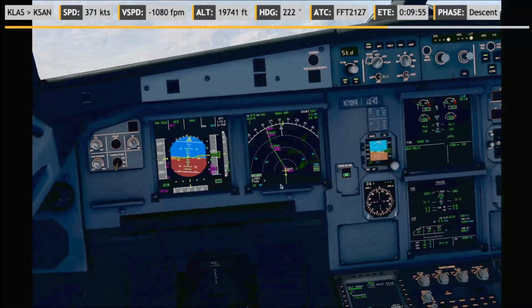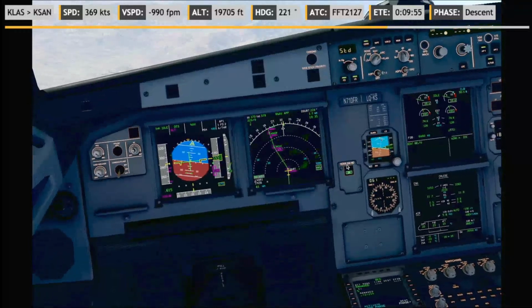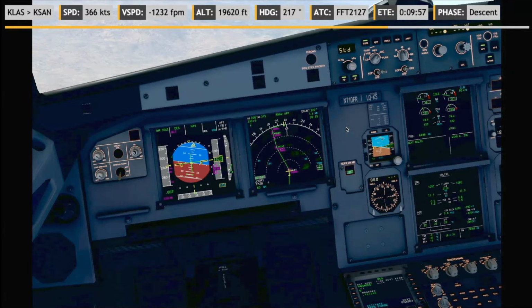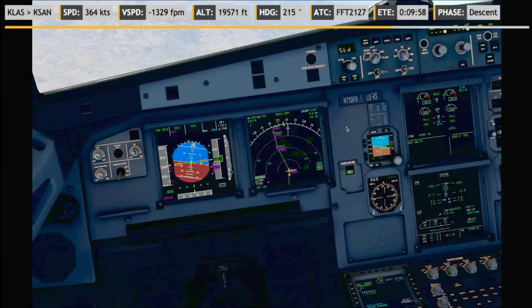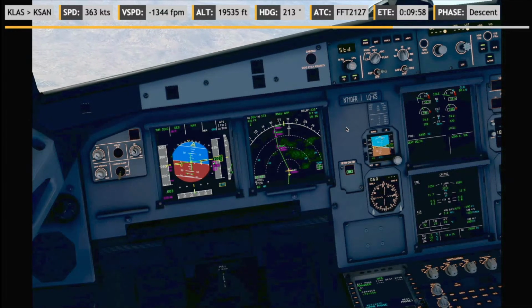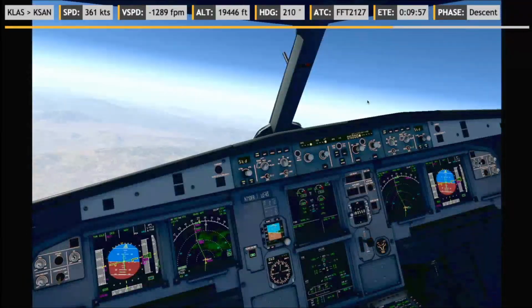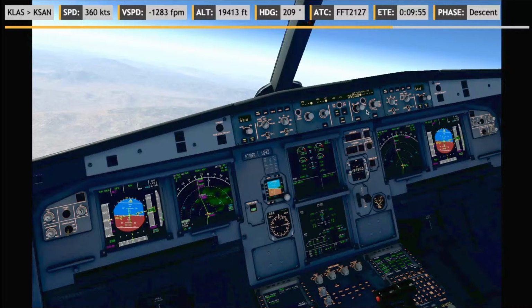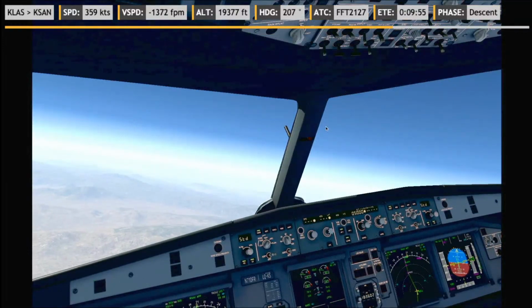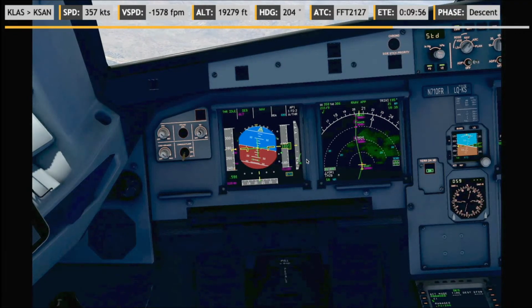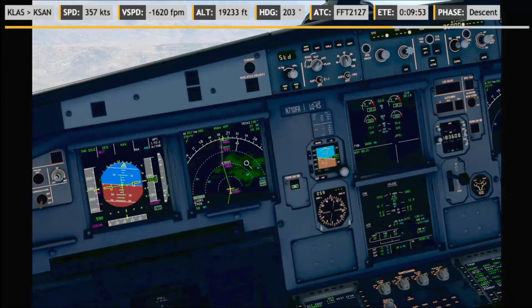190, but we're coming up on the next one. Next restriction is 12,000 feet. We're approaching 180, so we should be aware of the change in altimeter setting. That's what I was trying to say. It's not doing anything, and I don't mind us being a little high. Then we have to descend less, level off less, correction. And we use this leveling off to reduce our speed already to 270 knots. That's really, really smart of our airplane.